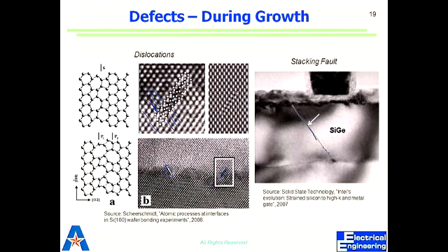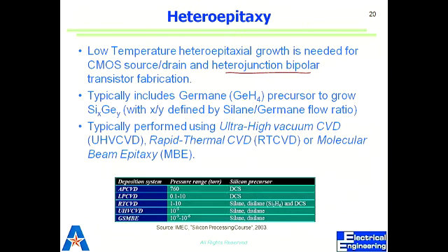By the way, if you look at these pictures, you can tell your friends that we can see atoms now. This is from 2008. And here again, they are under stress and they are causing those lines. If you see this line and this line, they are away from each other. Because of this dislocation, they are not really straight. On this side and this side, the crystalline structure has, because of stress, gone out of proportion. So these are defects which we see during growth.